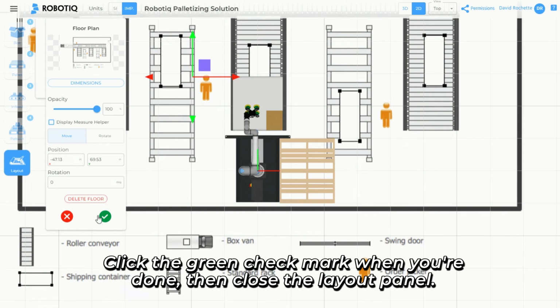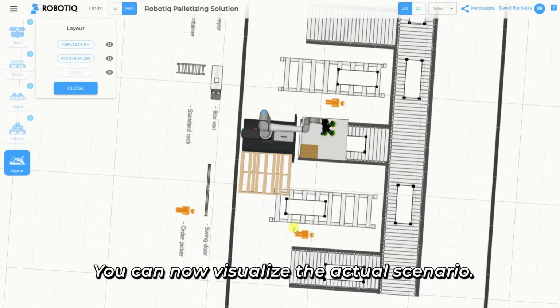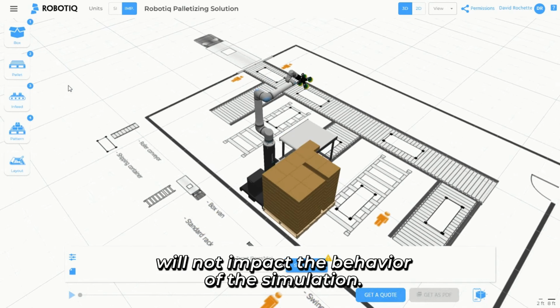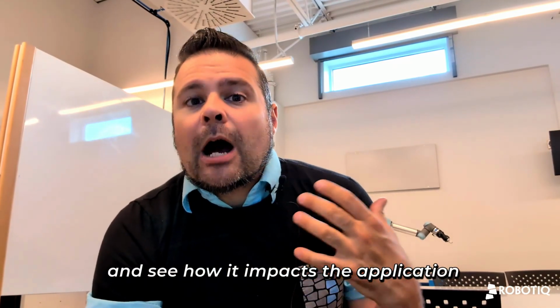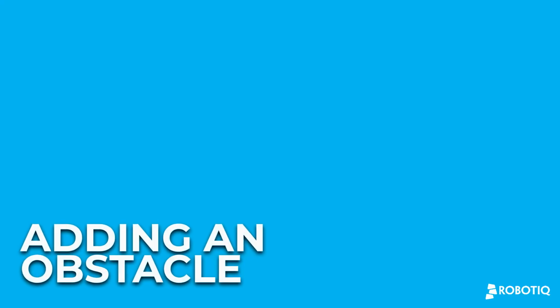Click the green check mark when you're done, then close the layout panel. You can now visualize the actual scenario. Note that this is for visualization only, and it will not impact the behavior of the simulation. To add an actual obstacle to the palletizing environment and see how it impacts the application, follow the next steps.